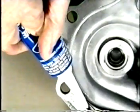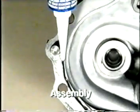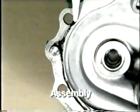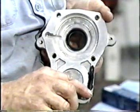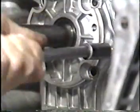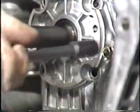When reassembling any transmission component, you need to apply sealant to cases, covers, bearing retainers, and many other parts. When applying sealant, be extra careful to apply small and efficient beads. Make sure to use the correct sealant. Silicone sealers are not recommended in some applications. Don't let any drop inside where it can travel in the fluid to clog lubrication holes.